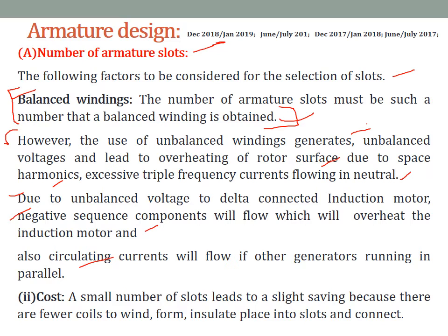Next, coming to cost, a small number of slots leads to a slight saving because there are fewer coils to wind, form, insulate, place into slots and connect.